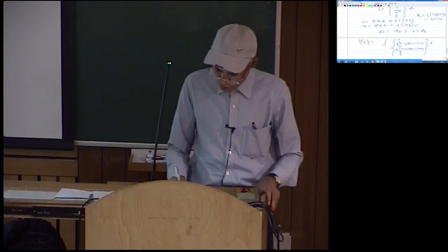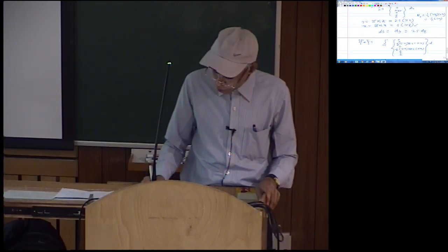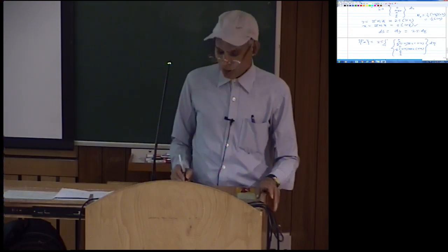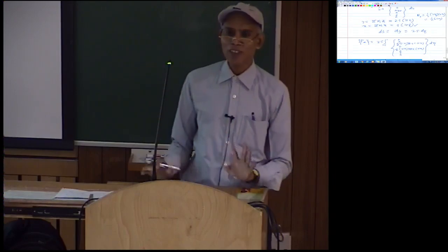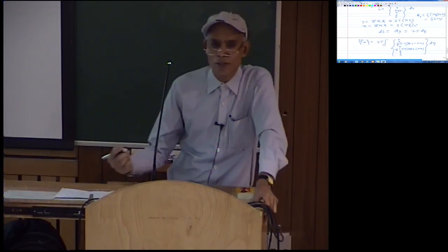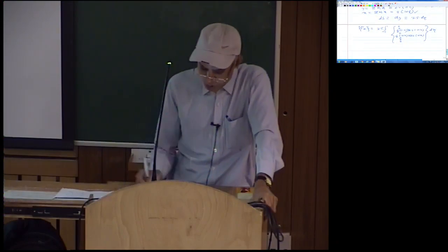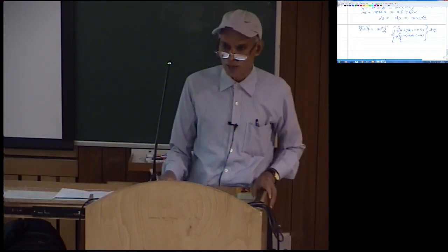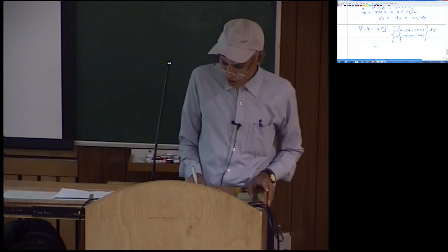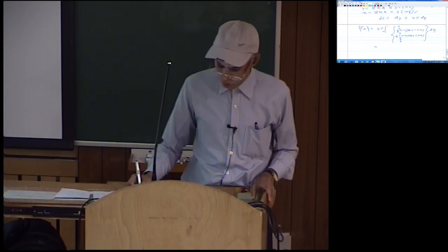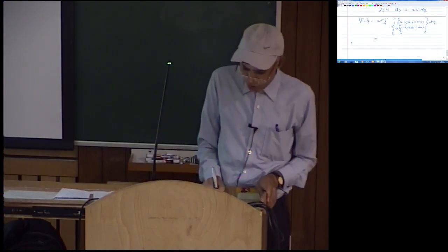And now ds is dy, which is 2.5 into d eta. So 2.5 you can say right here, and d eta. And then do this integration. Now there is no mention here whether you should evaluate this integral numerically or explicitly. So obviously it is easier to do the explicit integration here with respect to eta. So you just integrate this, and you have the load vector due to distributed force for the first element. So this integration you can do.